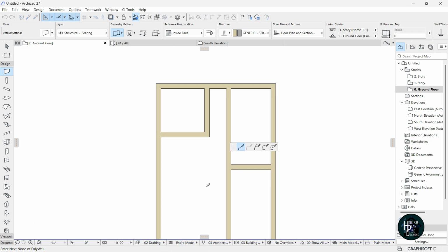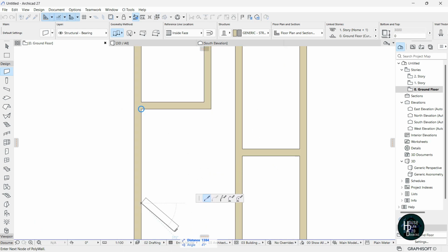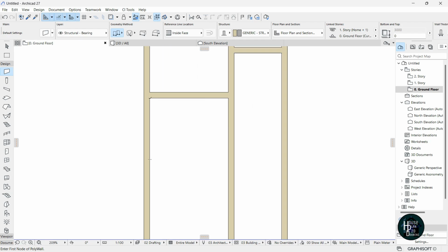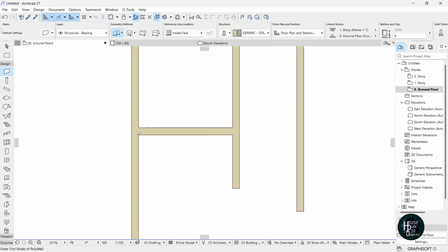Click enter, and this time around we want the wall to be facing outside by clicking this. Okay, then double clicking this side. Okay, now put the cursor here, allow it to load up, and let's give a distance of 4203. So click enter, just double click this side like so. Put the cursor here again, allow it to load up, and let's give a distance of 1172. Click enter. Okay, and let's give a distance like this for 17. Click enter and stretch it up.